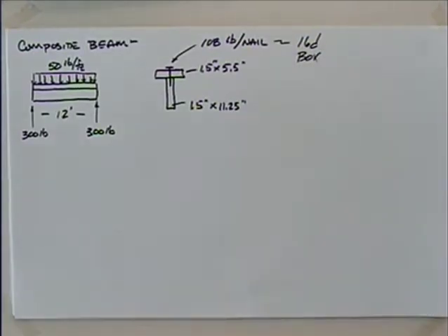So you could spend a lot of time talking about nail terminology and whatnot. If you go with hand-driven nails, usually there's two big categories for that. There is box and there's common. Box is usually more slender. Common are larger in diameter. Common are, of course, a lot easier to drive. They don't bend as easy. But remember, you buy nails by the pound, so you can get more nails if you buy box nails. So probably people tend to use more box nails. The numbers for box nails are slightly lower than common nails, but it's usually still more cost-effective to buy box nails. If you get into mechanically driven fasteners, pneumatically driven fasteners, then they usually go by different dimensions.